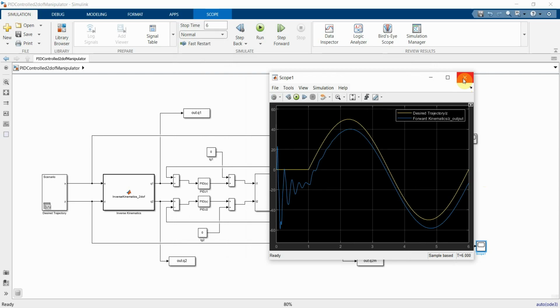As I mentioned previously, if you want to improve the model to reduce these vibrations and also remove this difference between the desired trajectory and followed trajectory, you have to use inverse dynamics properly. To do so, you either have to have knowledge of the dynamics of your robot, which is cumbersome and very difficult, or use tools like the Robotics Toolbox of MATLAB to calculate that for you. To keep things simple, I have not included that in this tutorial.